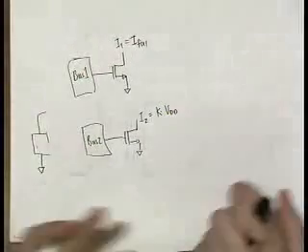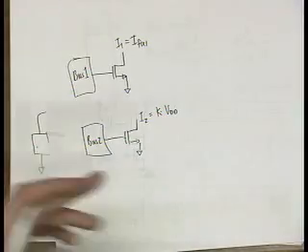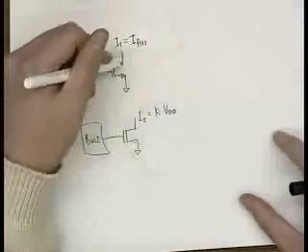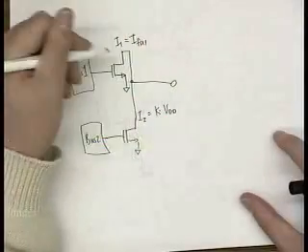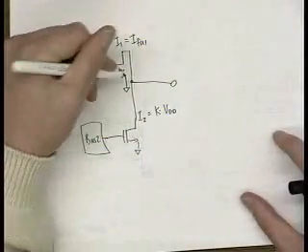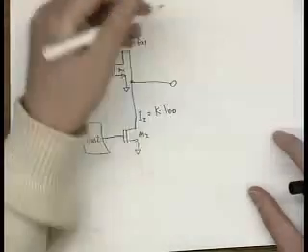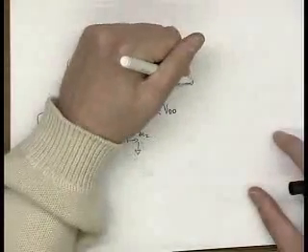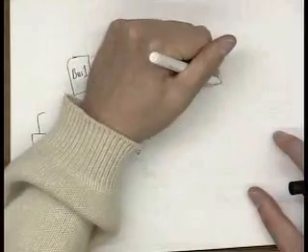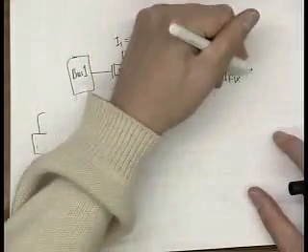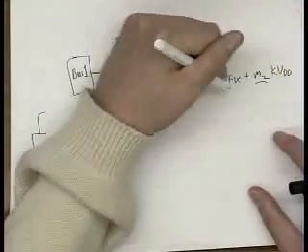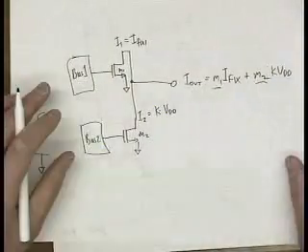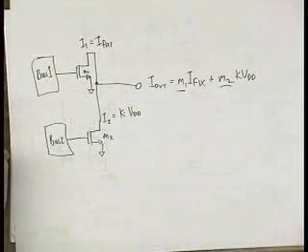Well, you need something that's mixed. How do you do that? In this case, it's really easy. You just sum these two together in the right ratios. You have M1 here and M2 here, so that you end up getting Iout equal to M1 times Ifix plus M2 times K VDD. So by choosing these mixing parameters, you can get the exact mix of fixed and proportional bias that you want.